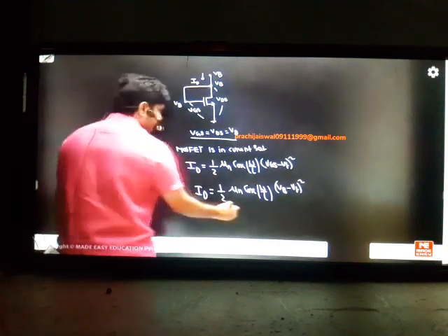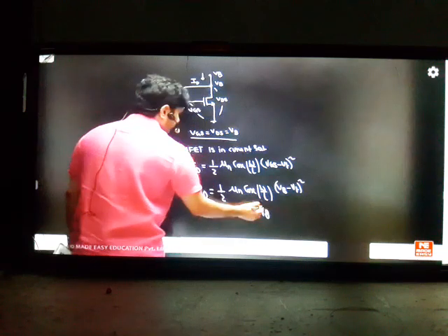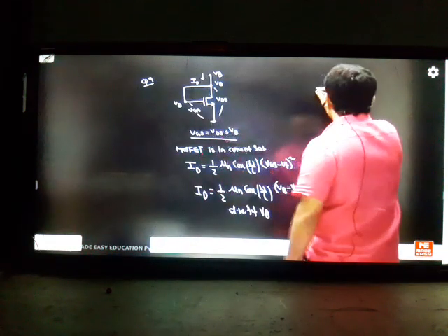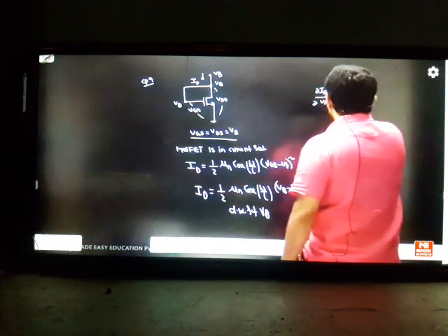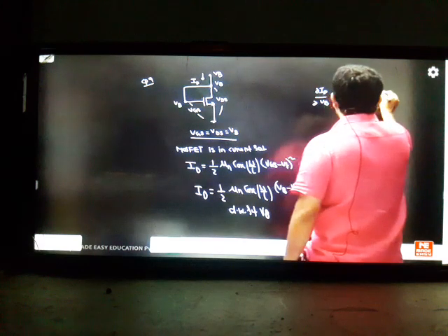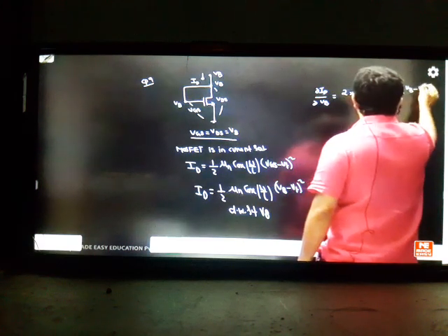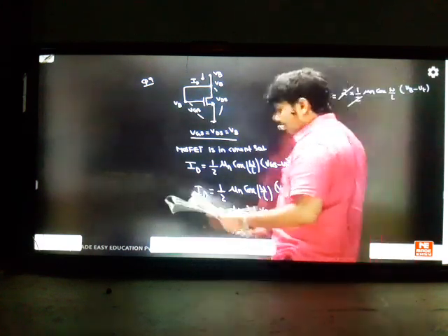So just differentiate this with respect to VB. Then the derivative of ID by the derivative of VB, first you solve this, becomes 2 into half into mu n Cox W by L into VB minus VT. So first finish that value.